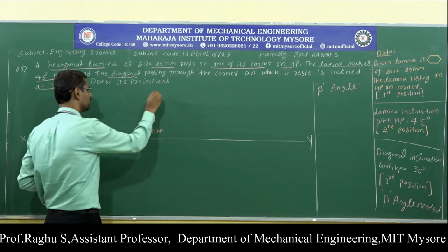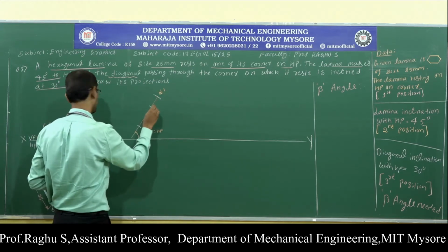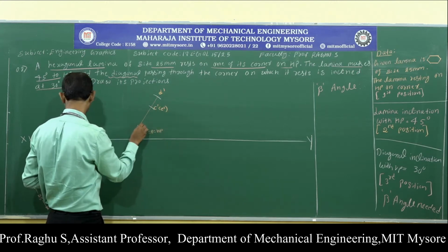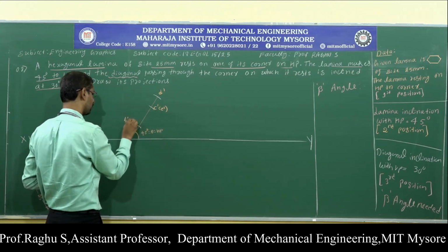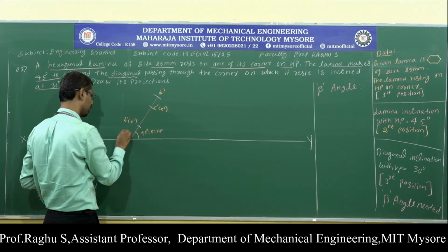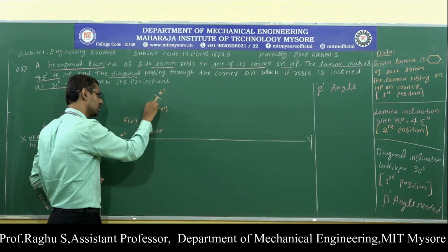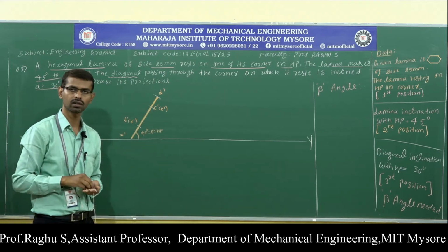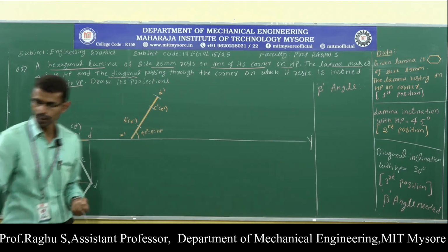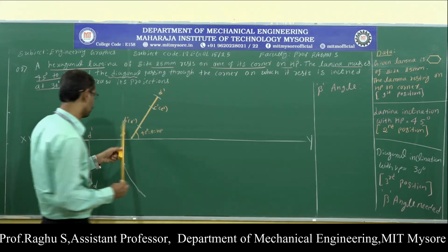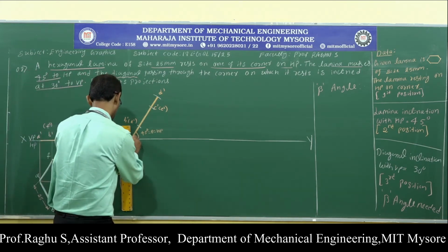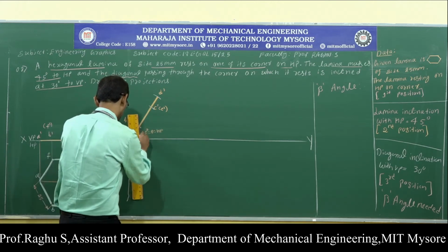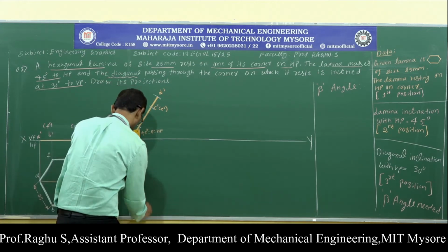Therefore, this is the point D dash, this is the point C dash and E dash, this is the point B dash and F dash, and this one is point A dash. Make it dark, since it is the second position front view. Next, draw vertical downward projections using thin lines. Projection lines mean thin lines.